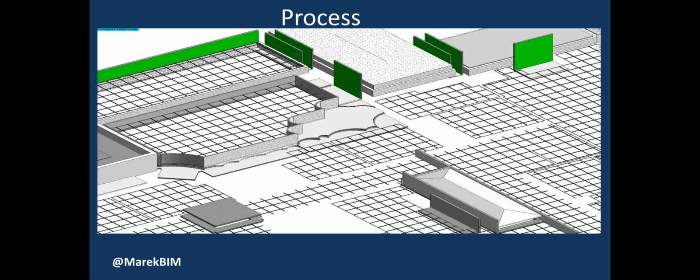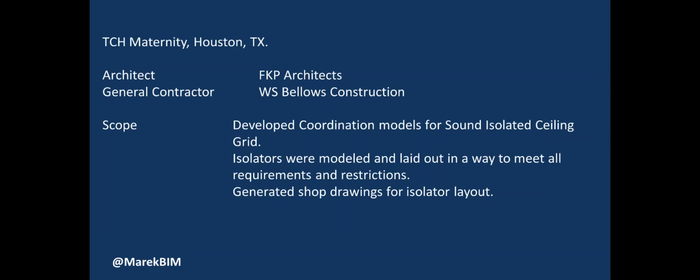Drywall ceilings we typically leave as a no-fly zone, a 4-inch no-fly zone. It's because the grid in a drywall ceiling can be manipulated, and this avoids any issues.